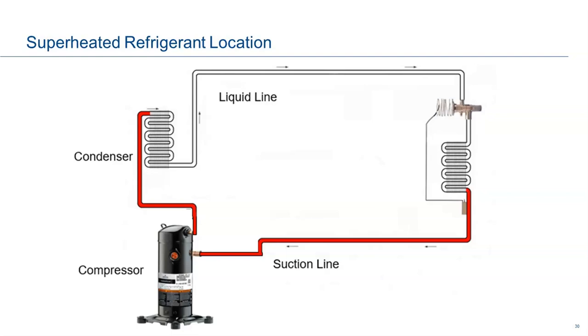So it gets hotter than it's supposed to before we ever get it. It's definitely running outside the envelope, and I can assure you that if it's 235 or 245, it definitely has a high compression ratio, which means nothing more than your discharge head pressure is too high and your suction pressure is too low, or both of them, okay?